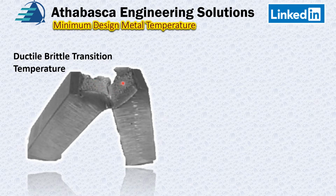It's associated with a lack of bending or pulling, and the surface is very indicative of cracking, which means it didn't stretch or pull, it just failed in cracking. Materials people have a problem with this kind of crack because this kind of failure can occur very suddenly and result in a catastrophic failure.